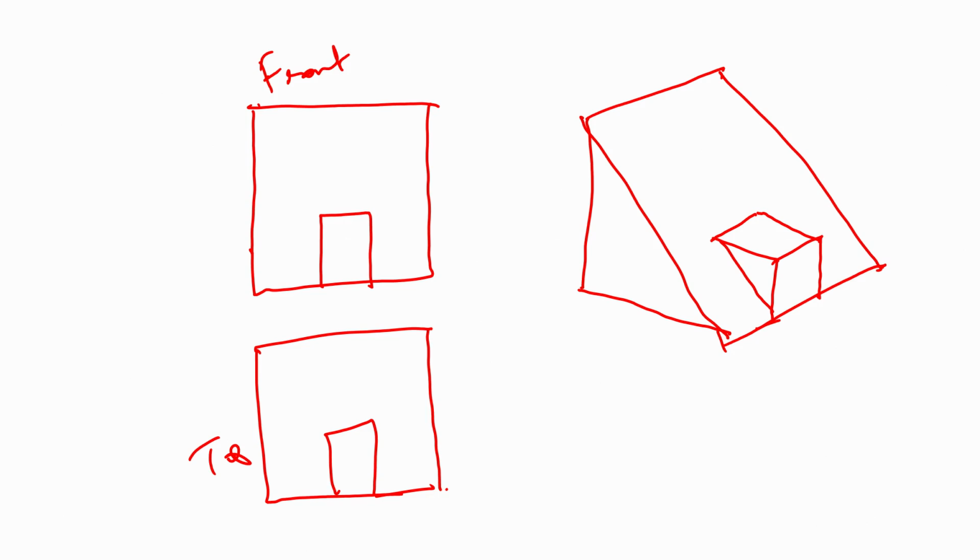The only problem which we may occasionally end up with is dimensioning, as earlier. For convenience, I will take something which is very easy. I will say the width of this solid is 30 millimeters, and this feature is 10, this feature is 10, this feature is 10, life is solved. Similarly, height, one more time, I write saying the height is 30 millimeters and this height is 10 millimeters.